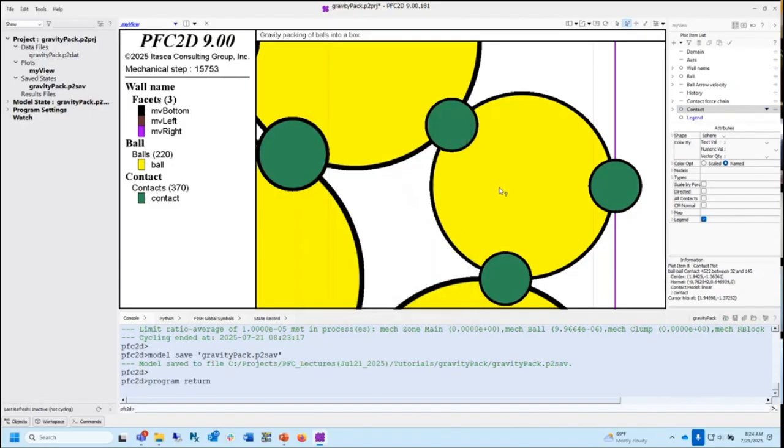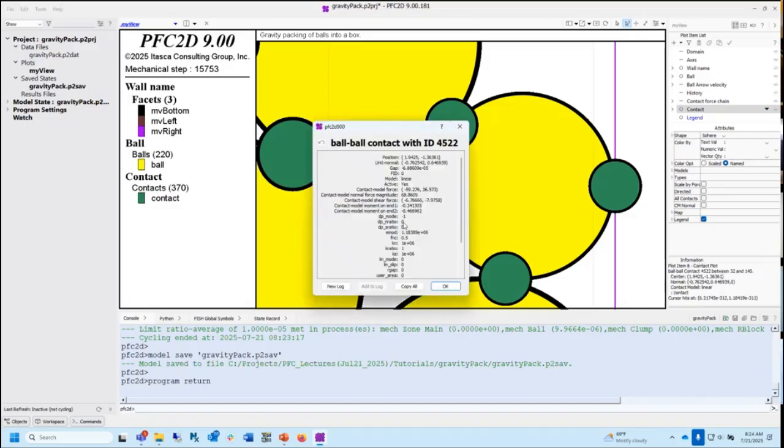Okay. Now let's look some more. Click on this. Oh my God, it's everything. Position, unit normal direction. Let's look at the friction coefficient. Contact model. Where is that thing? Right there. I can't make this bigger, but right here, these are contact model properties. Friction, 0.5. Okay.